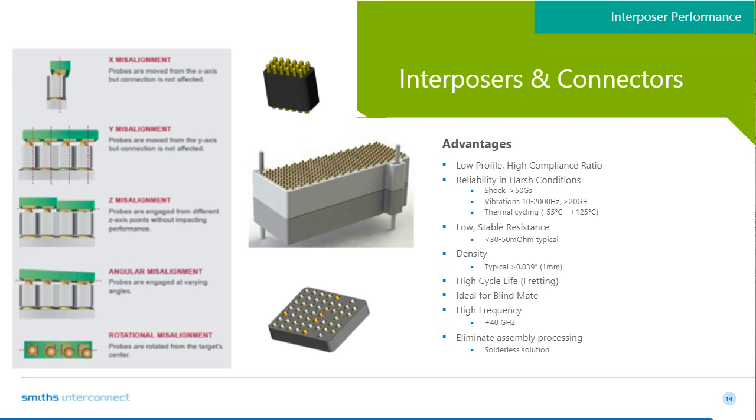By far, the most common application and purpose we design for is the solderless interface, as I've mentioned. And by that, we are typically using a double-ended spring probe where the customer's board application would basically have target pads on both boards, and the act of compressing the interposer between the boards and being held mechanically to maintain that compression ensures the signal pass freely. This offers many benefits.